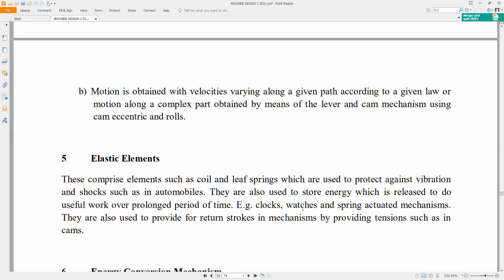What the camshaft does is only push the poppet valve down for the valve to open. But the spring, which is an elastic element, restores the valve back to its initial position to close the valve. If there is a spring loaded member and you push it down, the spring stores the energy used to push it down. Then the spring returns the object back to its initial position using the energy stored within it.